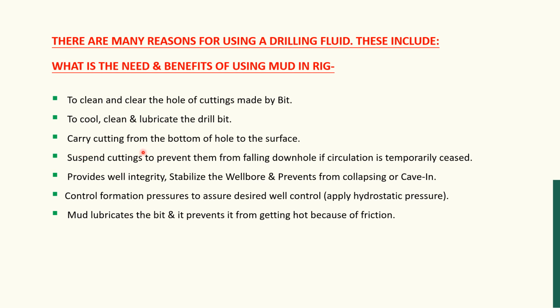Carry cuttings from the bottom of the hole to the surface. Suspend cuttings to prevent them from falling downhole if circulation is temporarily ceased. Provide well integrity, stabilize the wellbore and prevent it from collapsing or caving. So actually the drilling mud also plays a role here.